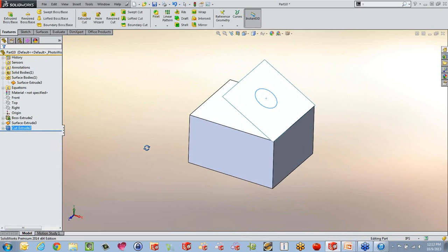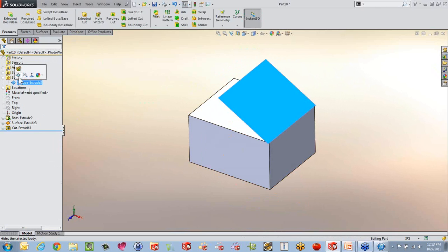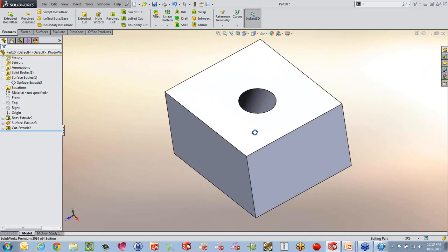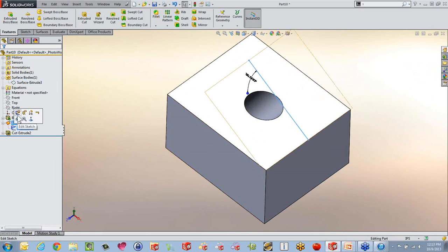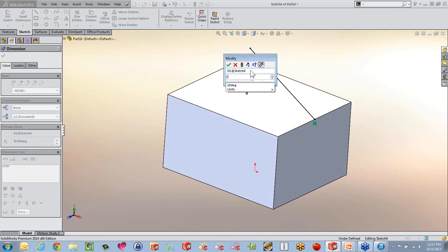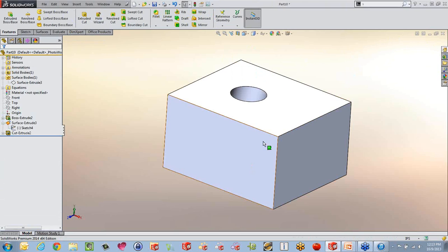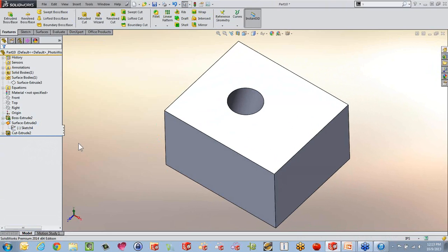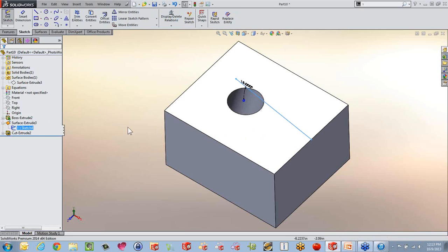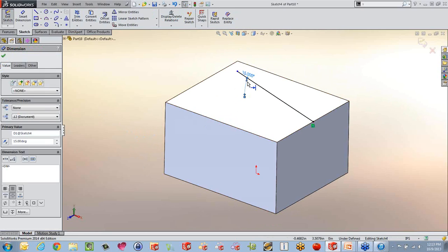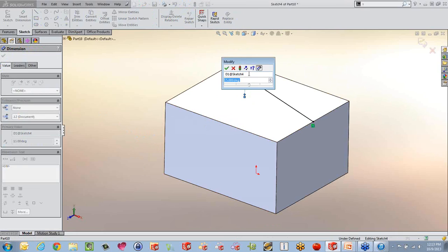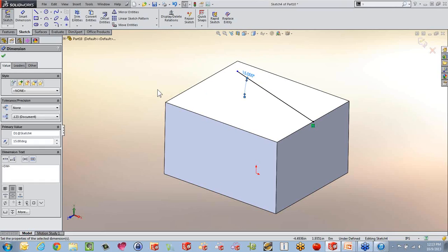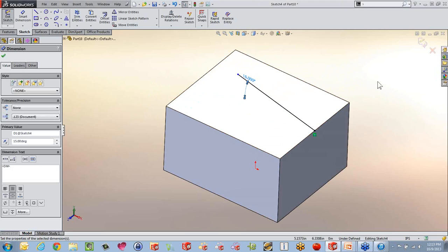Now extrude and cut through here. It's very common when we talk about surfaces to sacrifice surfaces or maybe just hide the surfaces. The hole is still there, right, cutting through. And now if I edit that sketch, I actually have that angle right there. So that's one way you could use a surface as guidance for the angle of a cut. This is legit; it's not necessarily a bad modeling practice. You could be working with different holes, and this is the way you prefer to control that, or do it with equations or whatever you're up to. It's important to know these surfacing tools are right there and available.